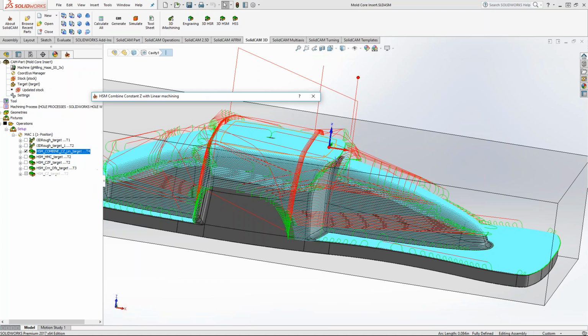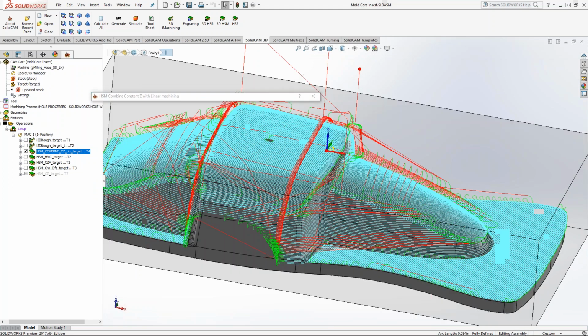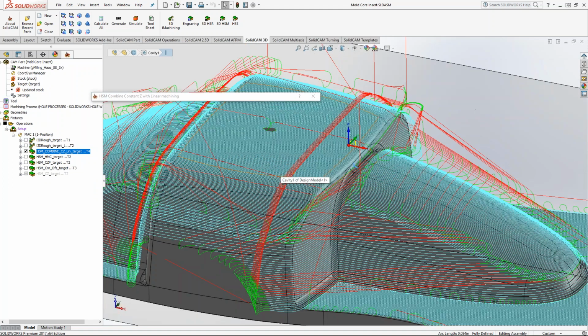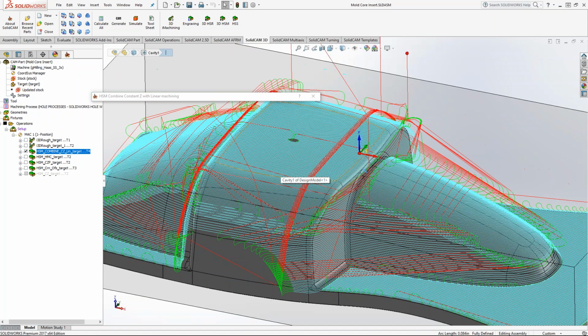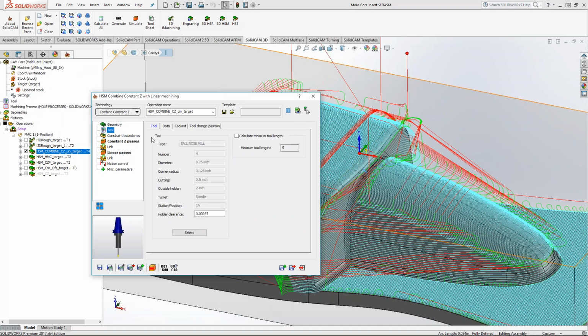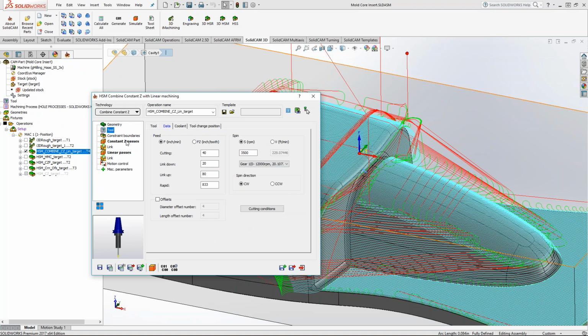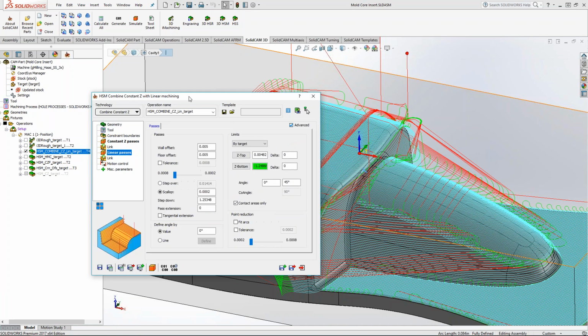And then when you go to do that, what were you running for feed rates on this? Feed rates on this one was probably pretty consistent with the other one. Actually, I slowed this one down here on the tool. This one may have been a little bit harder. It may have been maybe a H13 at about 50 Rockwell, I believe. That's why I slowed it down. Okay.